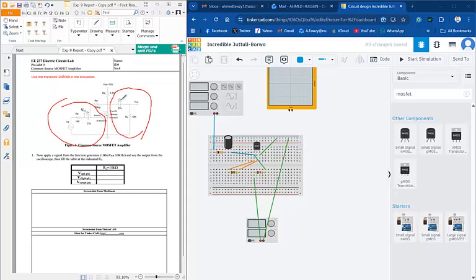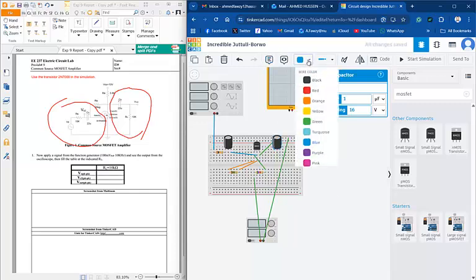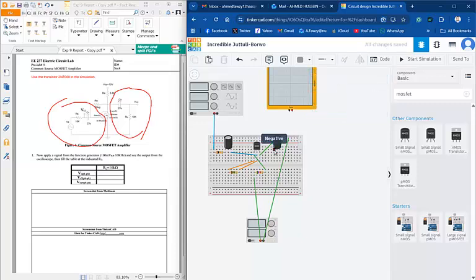We are left with a capacitor and a resistor. So I'm going to copy this one and put it on the other side. Get another color. Here is the negative, but we need the positive, so I am going to flip it. So it has become positive right now. The positive is connected to the drain. Okay, where is the drain? This is the drain. On the same line, I'm getting a wire from the positive to the drain.